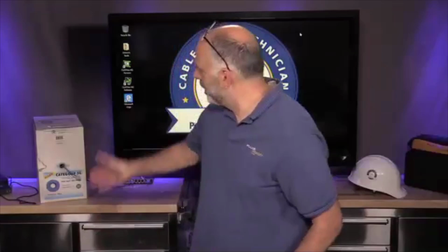One of the things that happened was there were some features on the DTX that didn't get over to the Versiv, especially with the DSX 8000 or DSX 5000. So one of those features that's been added in with 6.2 is the ability to do a spool test. For example, I've got a box of cable back here. If I want to test that box of cable, I want to do a single-ended test. I don't want to put a remote at the other end because getting the other end out of there is going to be a pain.